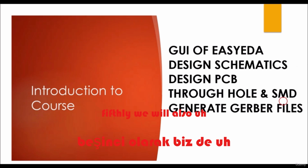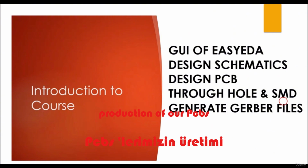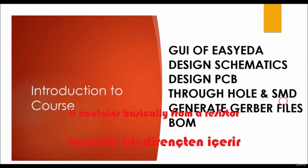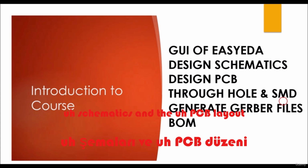Fifthly, we will also learn about the generation of Gerber files. Those are basically the files that we send to the fabricator for the production of our PCBs. And we will learn about the generation of the bill of materials. The bill of materials basically consists of all the components that we have used in the schematic. It contains everything from a resistor, capacitor, inductor, up to any IC with any number of pins. So it contains each and every component that we have used in the schematics and the PCB layout.